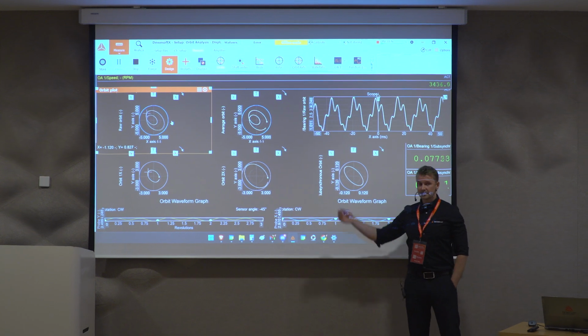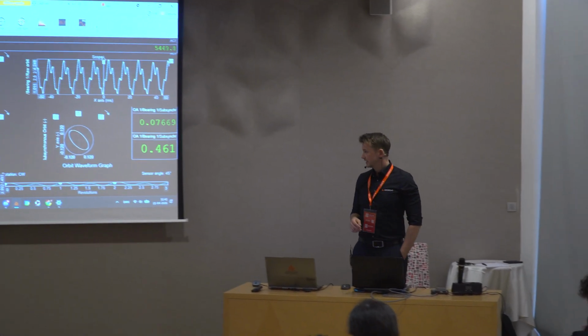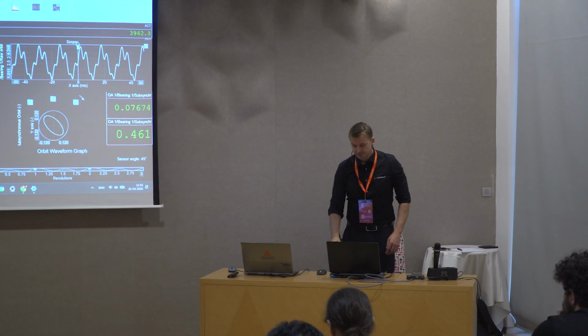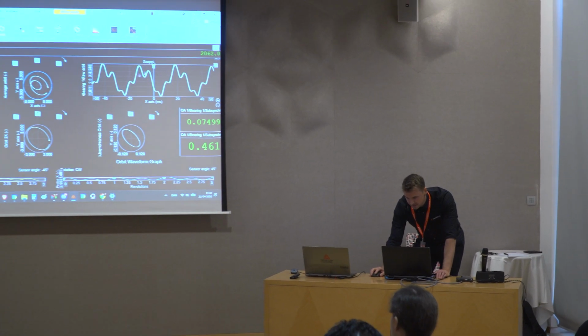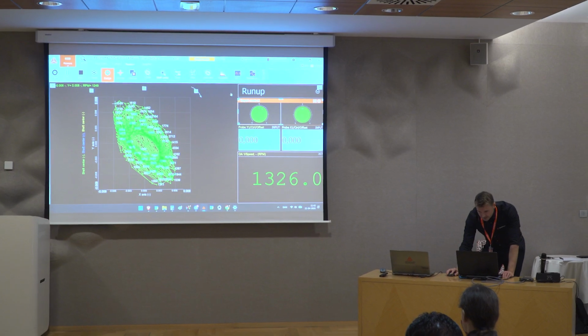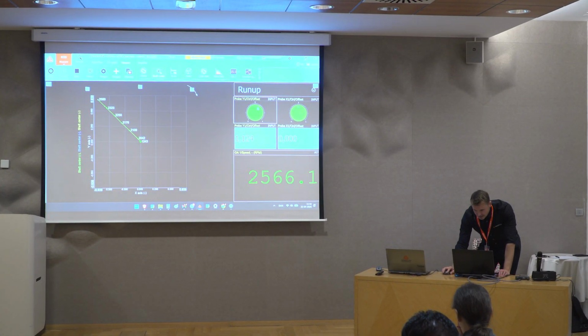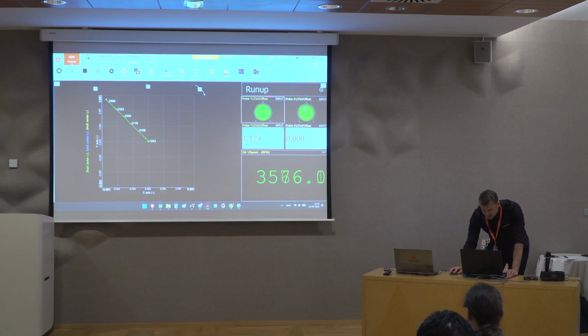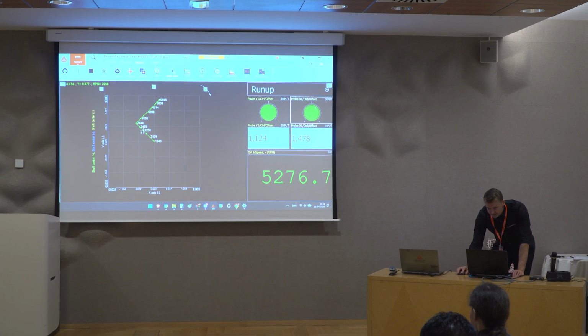That is called the second harmonic, or the 2x. And there you will also get an indication of the amplitude and the start of the phase. And together they create a signal like this. This is just a simulation, so if we imagine that you change the offset of the shaft, you can then follow the position of it together with the speed it was at.